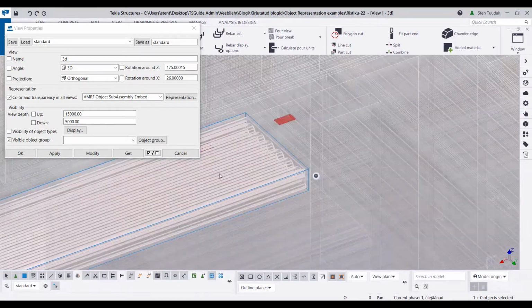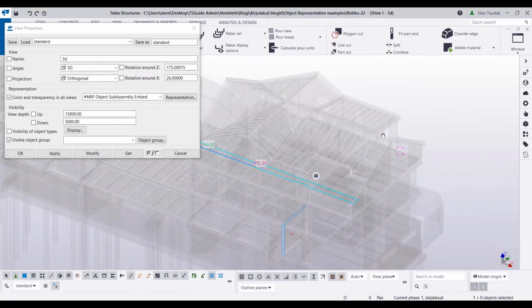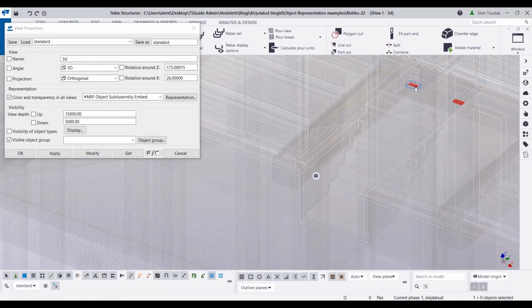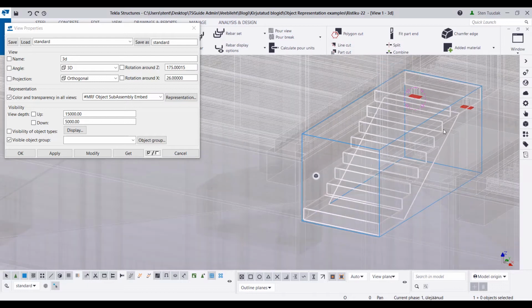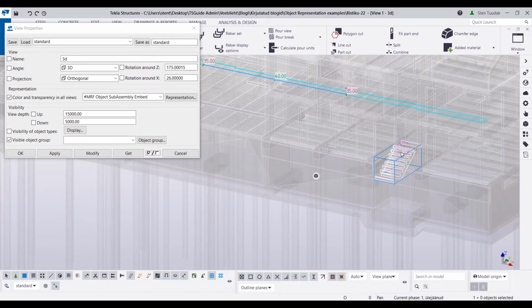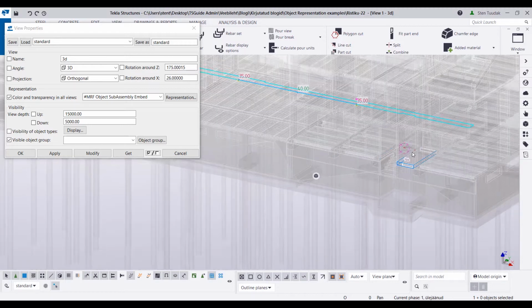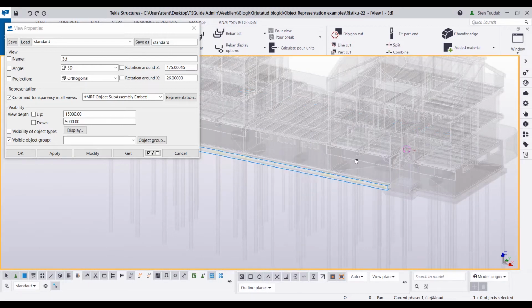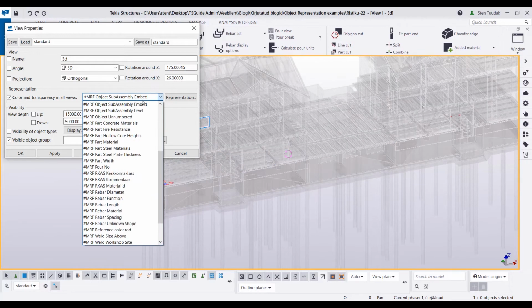Here we also have 2 plates, and they grab attention nicely, and we can see that they are under this stair, so they are for installation, let's say, and they shouldn't be part of any cast unit, because they are separate plates that will be placed on the construction site. In this case it's okay, but at least we got our attention there.